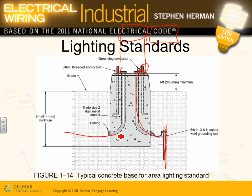When you bring your equipment grounding conductor, you tie it also to the ground rod. So what they do for sites, guys, they have an auxiliary ground rod right next to the light, typically every other light. That's for lightning protection. If lightning hit the lighting fixture on the pole, it will hopefully dissipate directly right next to it and doesn't get into the building.